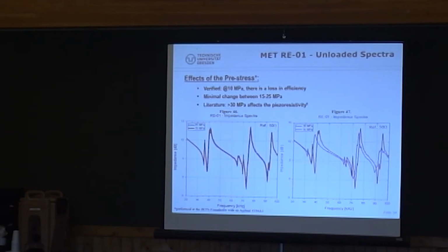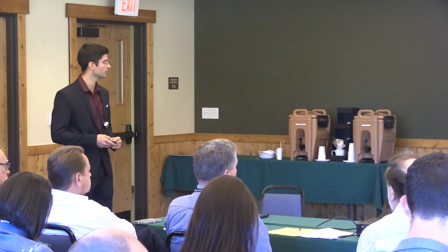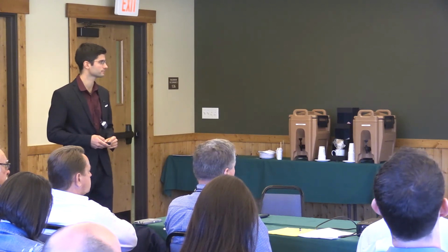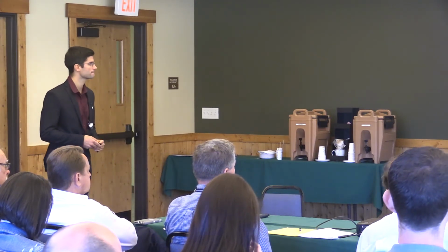Between 15 and 25 MPa is good. And from the literature, we don't want to go above 30 MPa, so we didn't, so as not to affect the material properties. And you don't want to be below 15. How much is that in psi? Yeah, 2,000 psi, I would say. But double check to be sure.